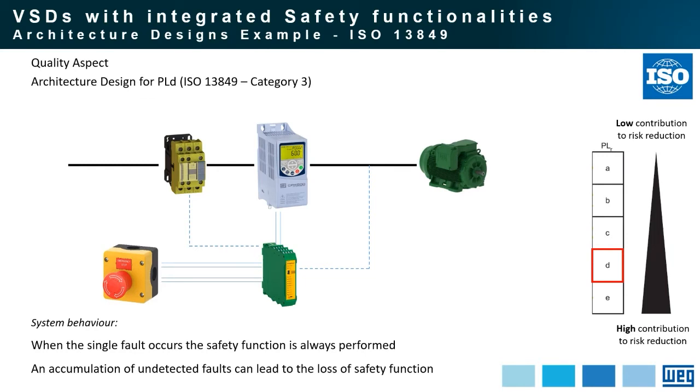And so in this system, when we have, for example, a problem with the cables between the emergency push button and the safety relay, the safety relay will set the warning. But again, a second cable, a second connection between the emergency push button and the safety relay, will make sure that the safety signal will be sent to the relay to stop the machine. So that is the meaning of redundant cables here between the emergency push button and the safety relay.